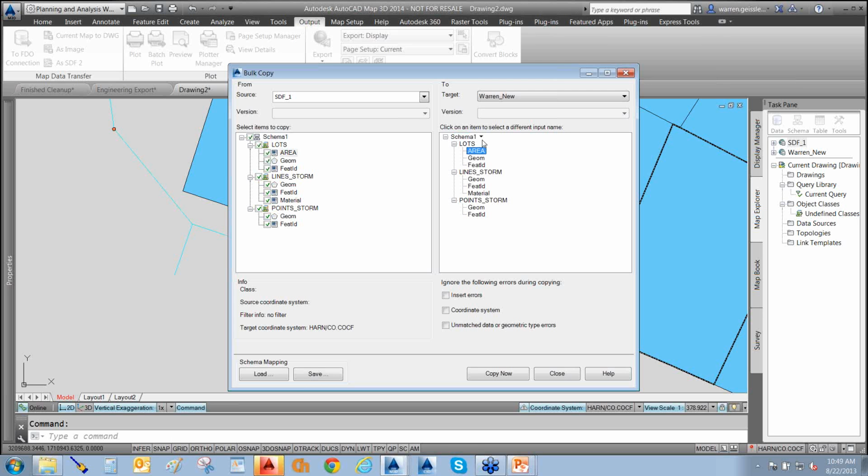The list drop-downs in 2014 are broken because Microsoft .NET Framework 4.5 breaks them. So if you uninstall Microsoft .NET Framework 4.5 and install Microsoft .NET Framework 4.0, these will go back to working.